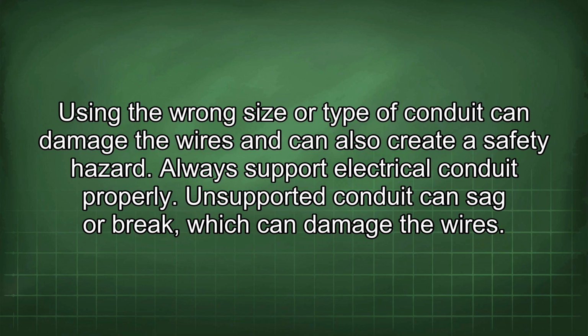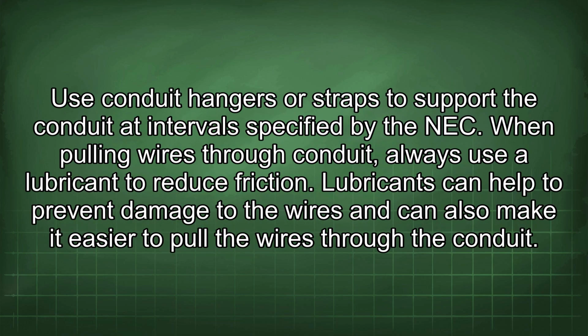Always support electrical conduit properly. Unsupported conduit can sag or break, which can damage the wires. Use conduit hangers or straps to support the conduit at intervals specified by the NEC.